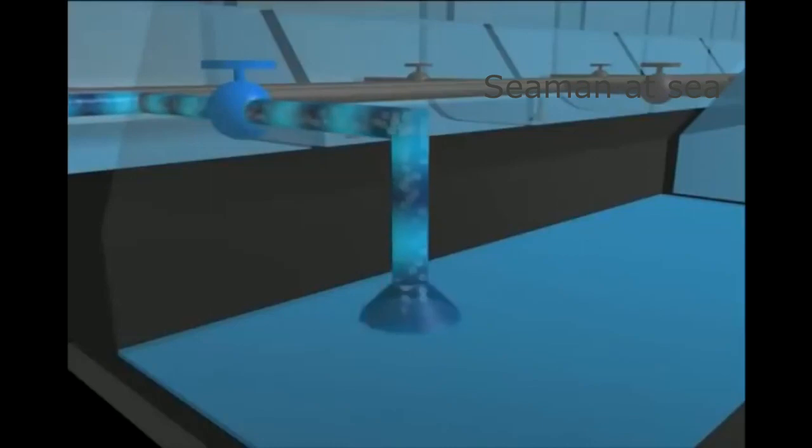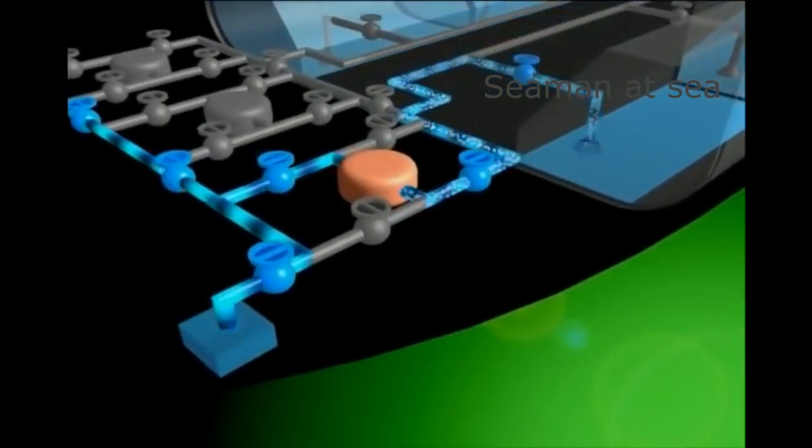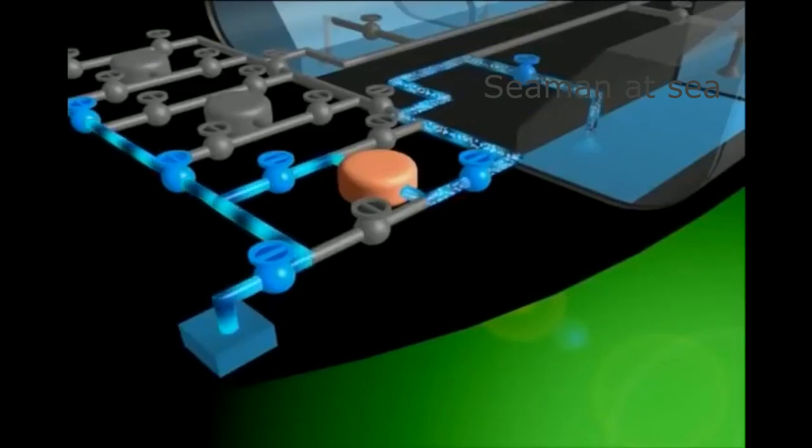If a pump draws in air while in operation, a noise is produced, and the amount of seawater discharged decreases, significantly lowering the pump's operating efficiency. Also, the amount of seawater being discharged will drop to zero in an instant once the pump has drawn in a large amount of air.